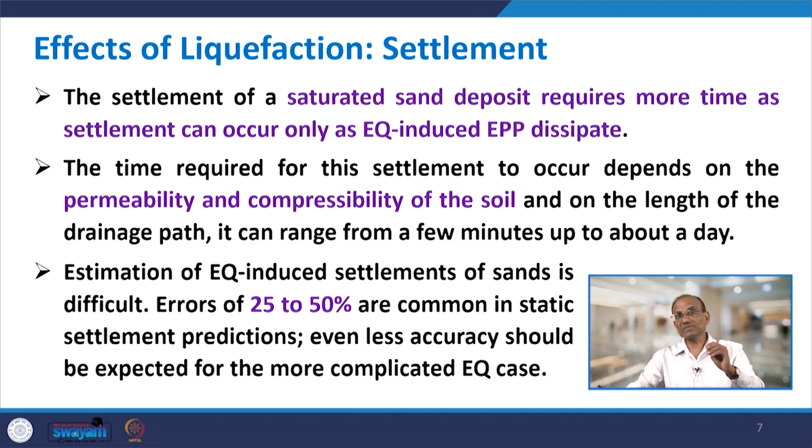However, the settlement of a saturated sand deposit requires more time, as settlement can occur only as earthquake induced excess pore pressure dissipates. There is a difference. When you have saturated conditions, it is not like air, which comes out when you apply pressure.